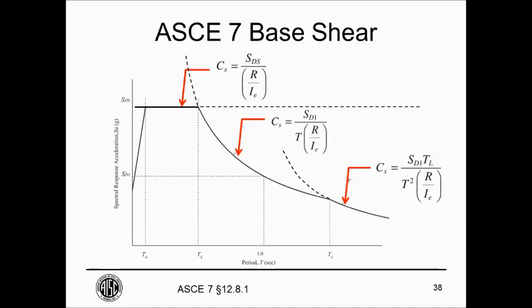So you can take an approach where the base of the structure is down at the bottom of a basement and you include the mass of the levels above, or you can take an approach where you're taking the base shear out at the ground level regardless of the presence of the basement, and not adding the mass of those subterranean levels to the base shear that you're taking out.